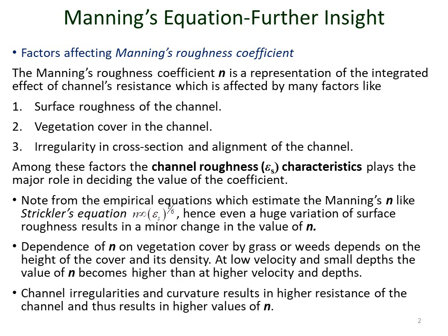It depends, again, on the experience of the person who is handling it. At low velocity and small depths, the value of n becomes higher than at high velocity and higher depths. This is also one important characteristic of the value of n when there is a grass cover or a weed cover on the channel bed.